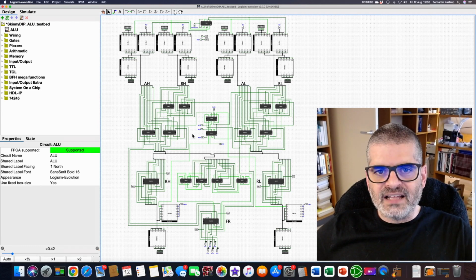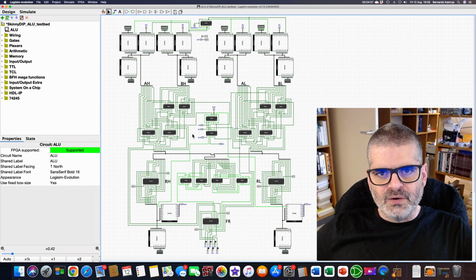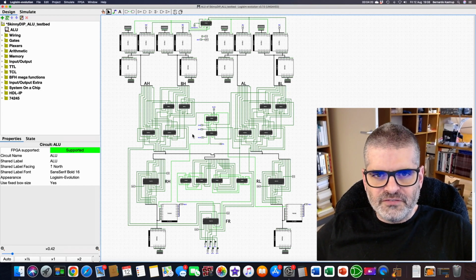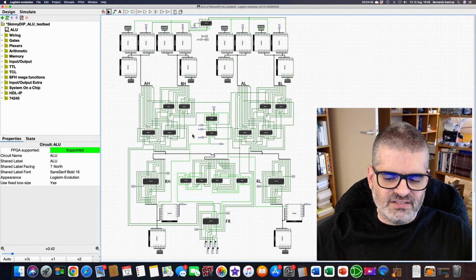But even that will only be done when we are designing what we call random logic or noodle logic, which basically means fine-grained and irregular logic, which is what you usually get when you're implementing a large finite state machine with lots of encoded states, and you have some Karnaugh map optimized logic on the side.